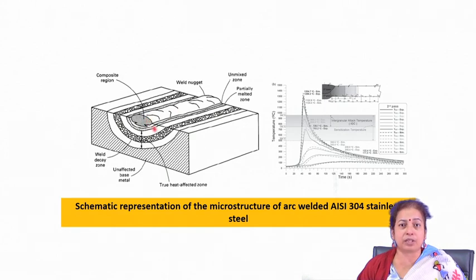So, it has a very good microstructure and does not undergo any intergranular corrosion after welding. But when you think about the heat affected zone microstructure, you will find that it undergoes a particular thermal history, where the temperature between 950 and 1450 degrees Celsius passes through 950 to 1050 degrees Celsius, which is the chromium carbide precipitation regime, for a long time, and as a result it gets enough time for the chromium carbide to precipitate along the grain boundary region.